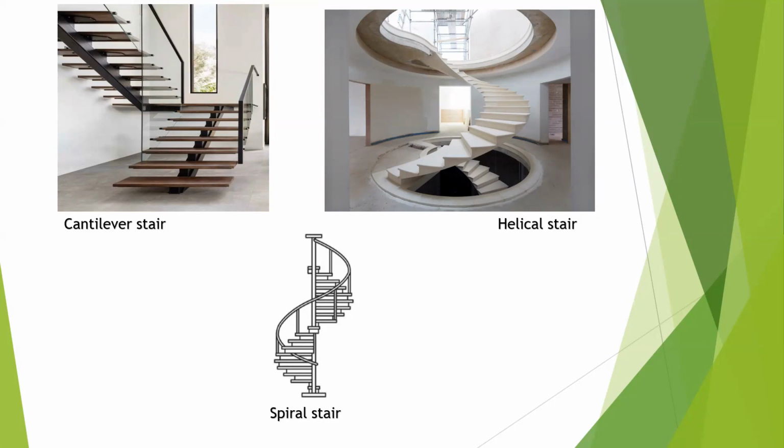When you talk about space utilization and cost, the spiral stair is the most economical, and it consists of several cantilever stairs coming out from a central circular column. And each of these stairs is designed as a cantilever.